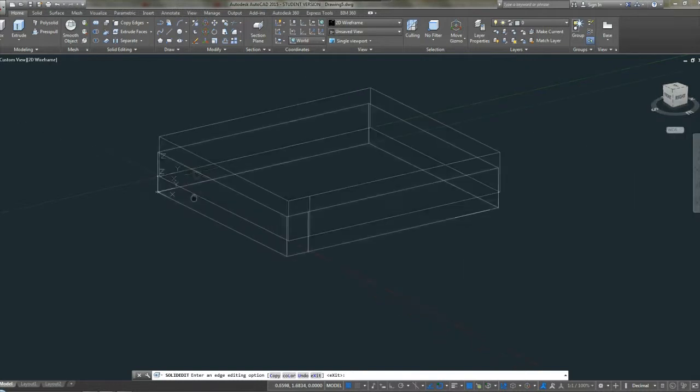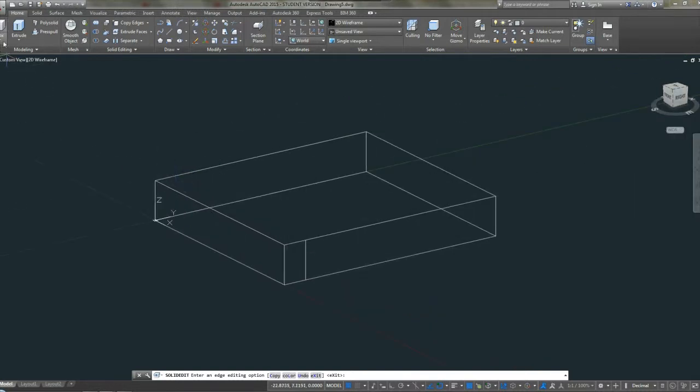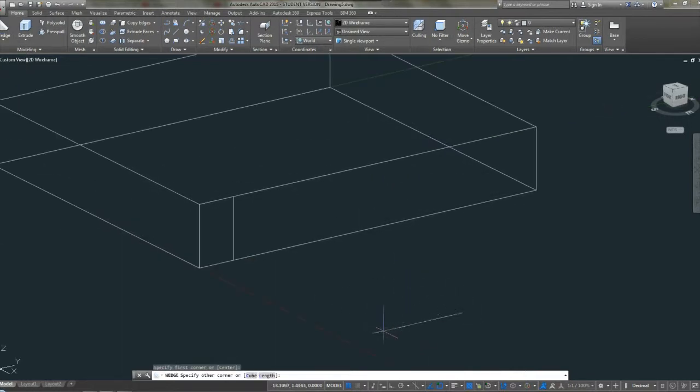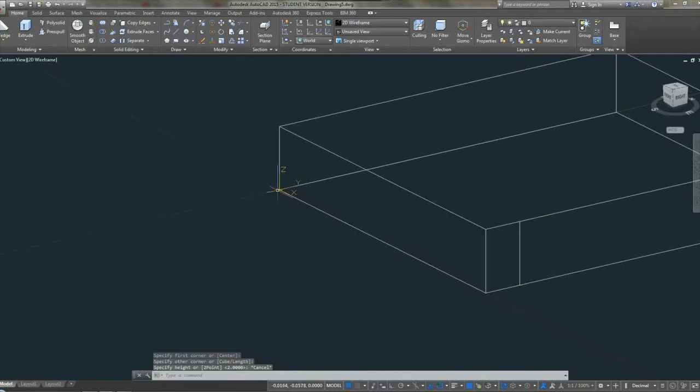And then with that, I will use the wedge command. But if you notice, when you do the wedge, it comes out looking to another direction, and we don't want that. We want it to go to the horizontal direction, because we want to cut off part of the box so it has that slanted look from the PS4. So you have to change the axis.